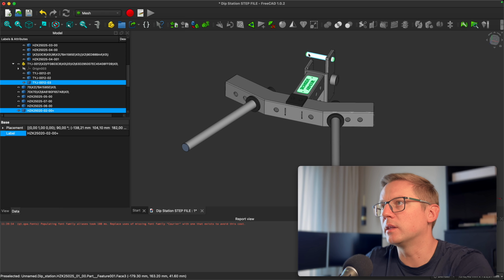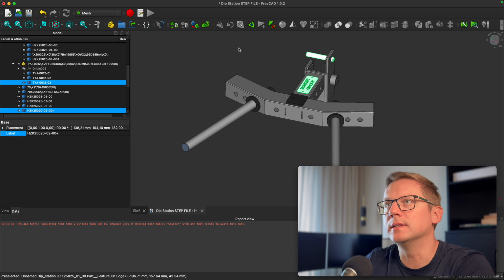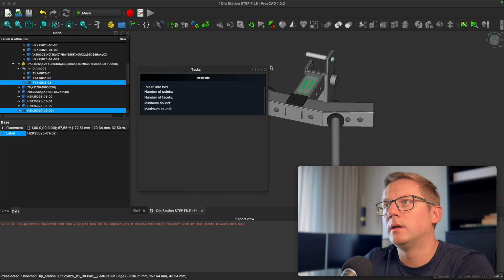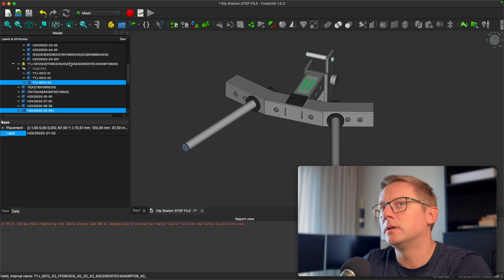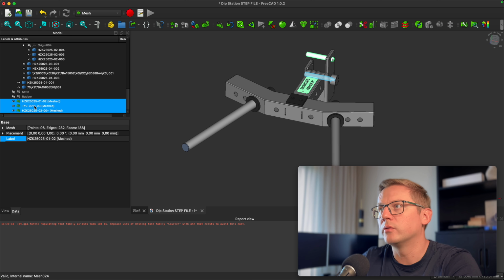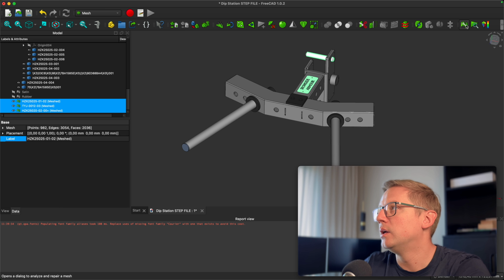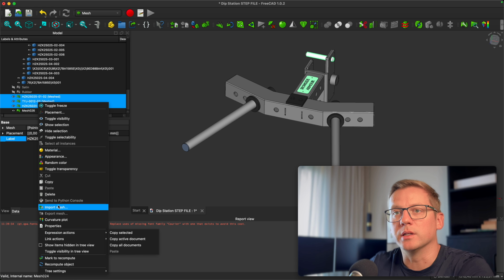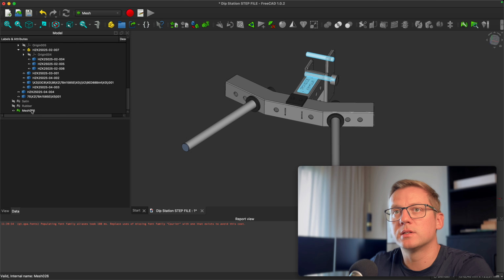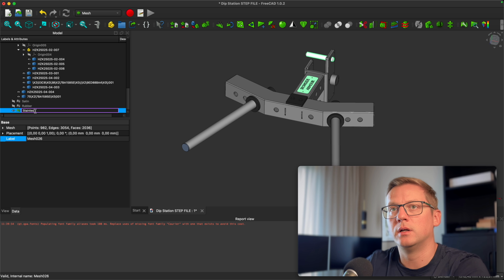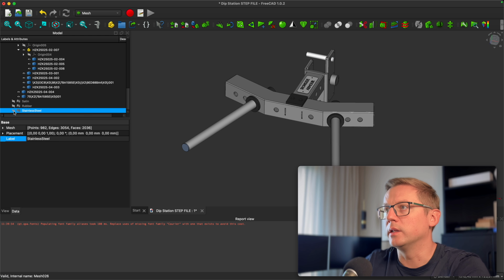Execute. I select everything that is stainless steel. Let's tessellate that. Let's close it. Let's go down. Here we see 3 objects, and let's merge them together in one. Let's delete the objects. Let's call it stainless steel mesh, and let's hide that as well.